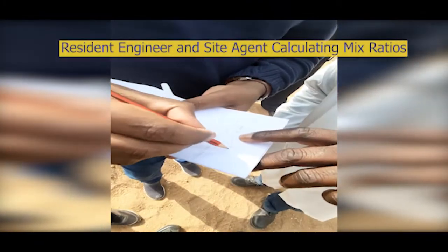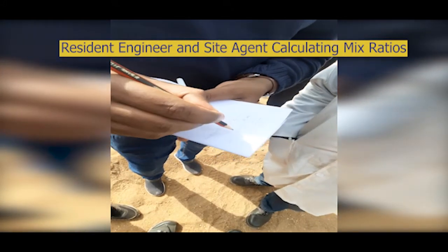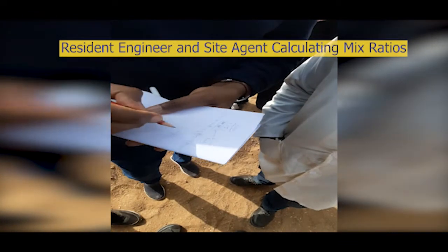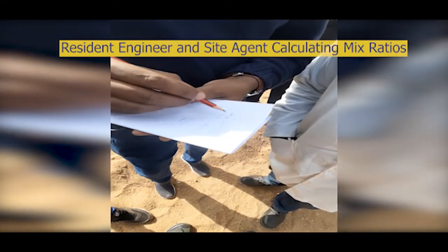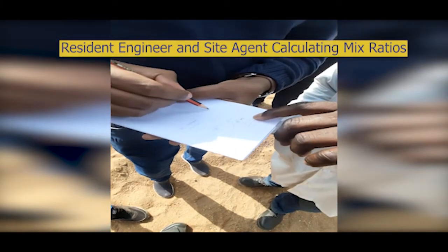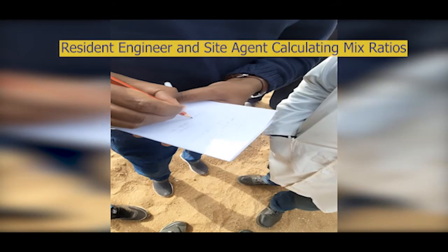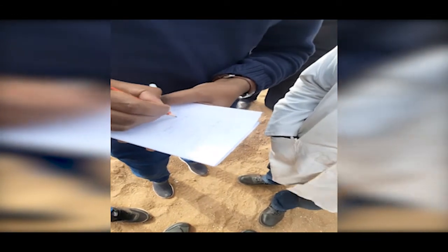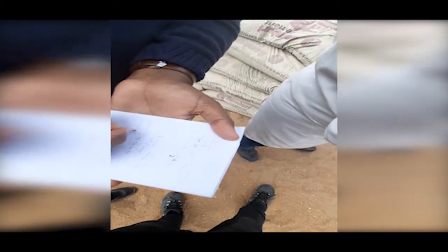Typically in volume batching, the materials are measured on the basis of volume. Do note that this method is less precise compared to the weight batching that we'll discuss shortly. In volume batching, you would use measurement boxes or gauge boxes which have predetermined volumes, and these are used to measure the materials.